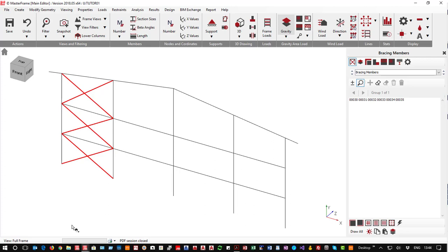Yeah, again, asking about bracing members, it is putting them into a bracing member group so they do not get wind loading areas. That is correct. So because these are in a wind bracing, if I was to go and put a wind, this is a wind panel, and say it was horizontally spanning, the wind would span from that member to that member and from this member to this, and not try and put the loading onto the bracing members. That is what we're doing here. We're saying bracing members, or you could argue members that never carry my area loading. Same thing.